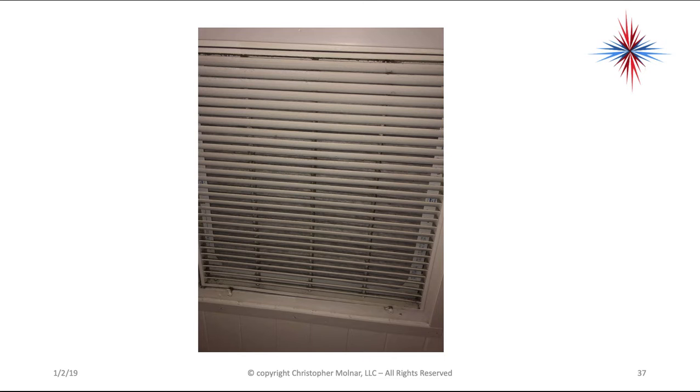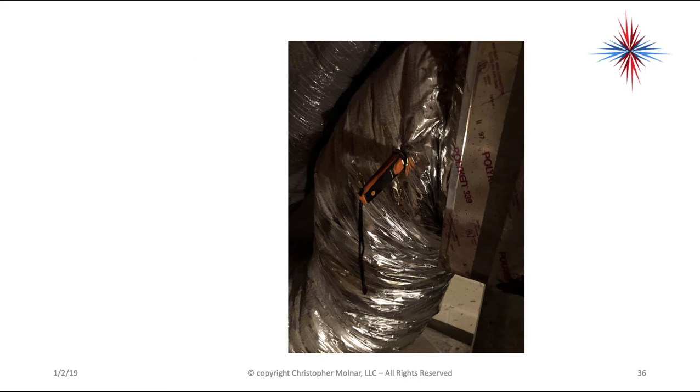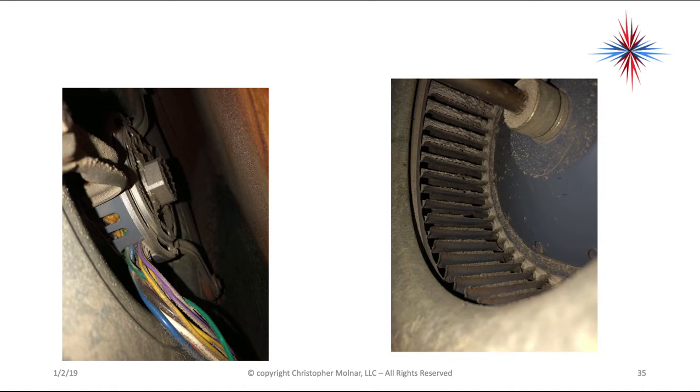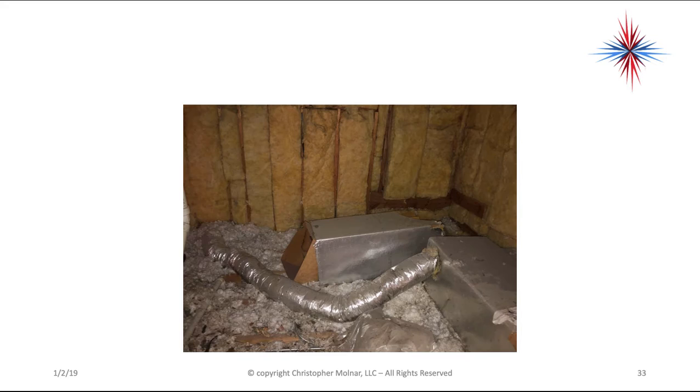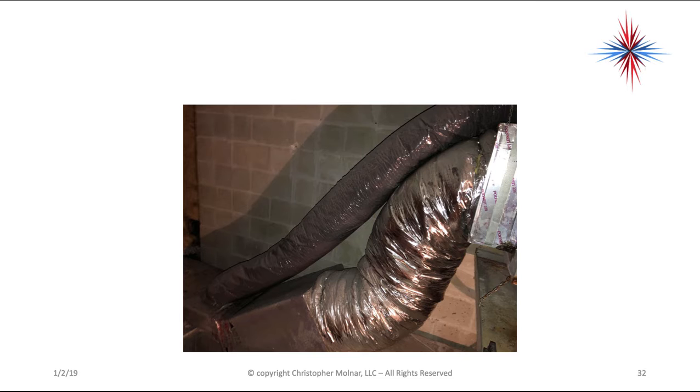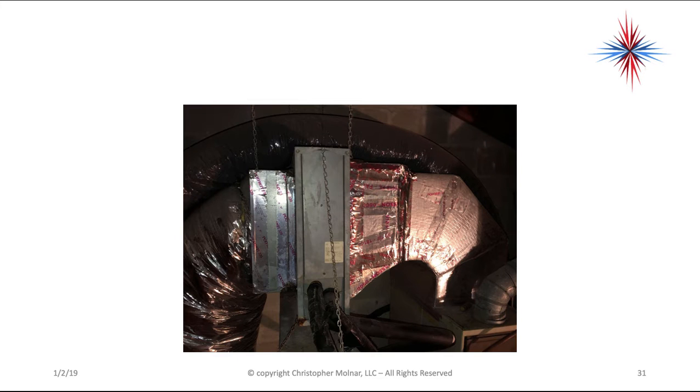But so if you go through this system that we just looked at, okay, the system needs to be cleaned, probably needs totally new ductwork, or at least tightened up, because everything is sagging, everything has some restrictions. Okay, needs new plenums on at least the left side of that coil.